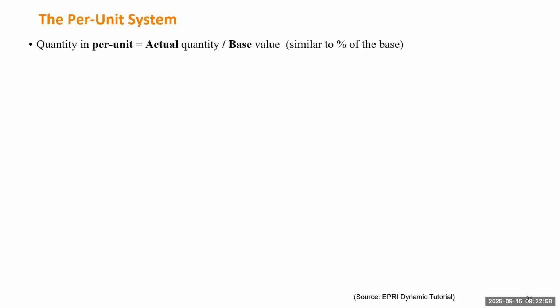But to utilize electricity, you have to decrease the voltage to the sub-transmission level under 100 kV, then give the electricity to a distribution system. So there are many voltage sections. Doing the calculation for such a power network with many different voltages can be very, very complicated. So that's a strong reason to introduce a per unit system.